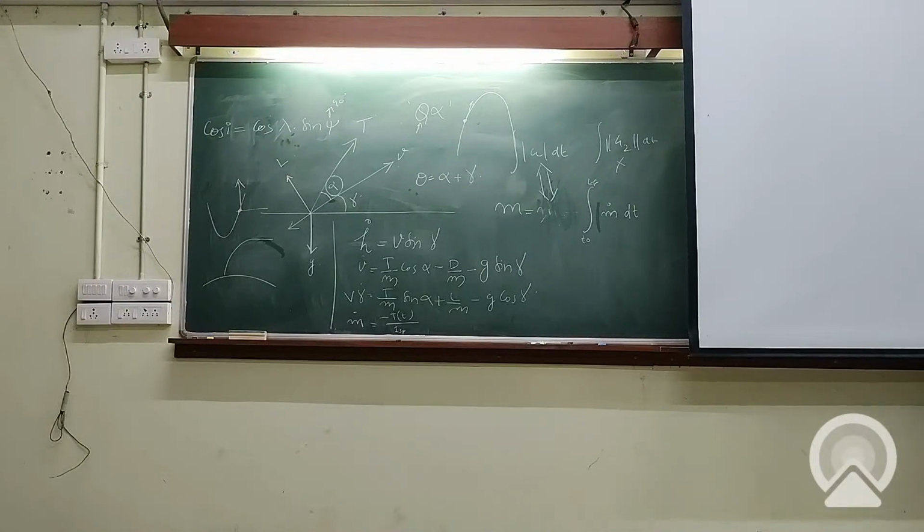Then we have the re-entry. You are coming back with a very high velocity. Now with that kind of velocity, if you enter the atmosphere, then the heat load will be very high, right? So you have to decrease the velocity. You do a re-entry burn. Then it has aerodynamic surfaces as well. You would have observed it has grid fins. So during the re-entry phase, it deflects the grid fins and has very good control over the range.